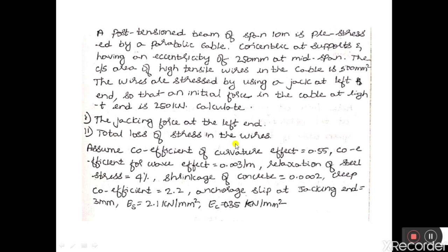The details they have given are the span of the beam, which is 10 meter, and the cable is having an eccentricity of 250 millimeter at the mid span. The cable is having a parabolic profile, and they have also given that the initial pre-stressing force in the cable at right end is 250 kilonewton.